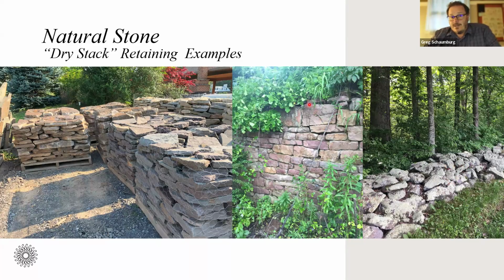And then oftentimes, one of the great things about it is, if you look through natural stone and spend any time driving around Pennsylvania, New Jersey, this was in South Central Pennsylvania, down around Harrisburg, Hershey area. But this was a wall that well outlasted the barn foundation that was there. And this was partially retaining and also partially foundation work, but semi-dressed fieldstone material that was from around the 1850s. The barn was long gone and rotted and fallen over, but the stonework, based on the way it was worked and installed, was still there and still pretty viable.